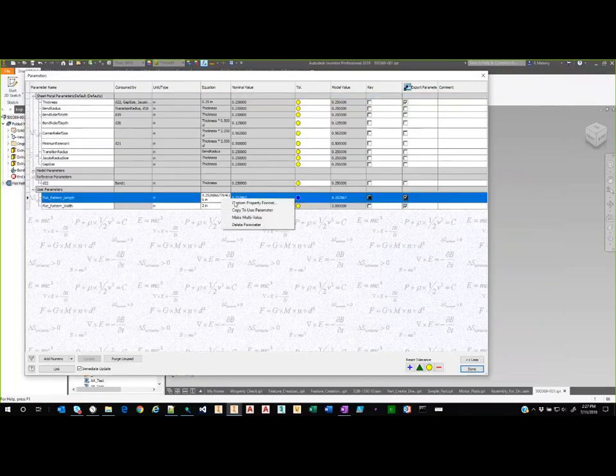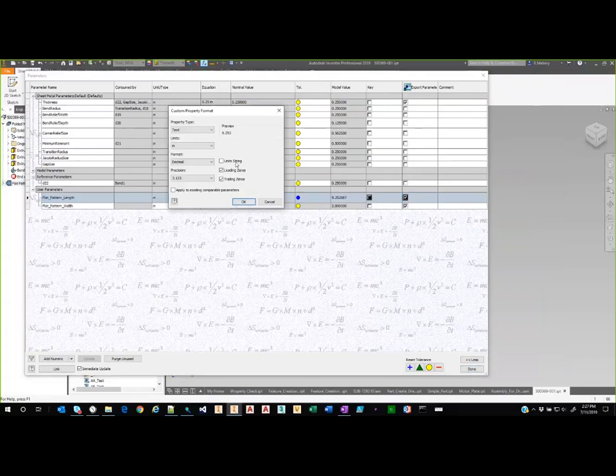They are set to export, and then, I turned off the unit string. I guess I left the trailing zeros and I set it to 3-place precision. Right, so you can control any of that stuff that you end up wanting. If you want to change the format to fractional, right, all of that is possible doing that.